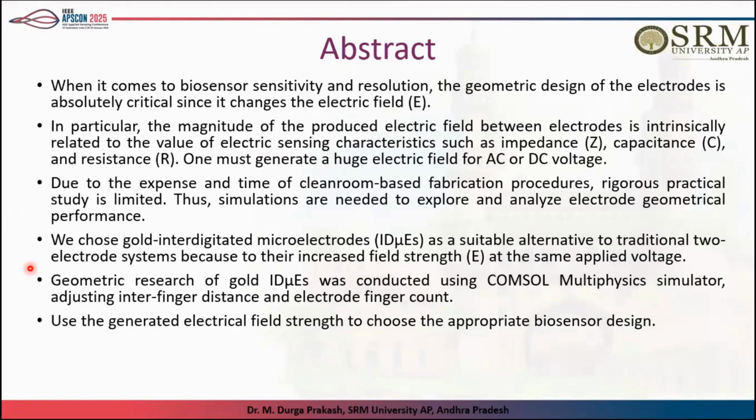The brief abstract of this work is as follows. We know that in any biosensor, we are looking majorly at sensitivity. The sensitivity matters, and also resolution. Particularly for that, we have designed and simulated the geometrical design of interdigitated microelectrodes, looked at what changes occur in the electric field in the sensors, and also seen the different sensing characteristics of the device, like impedance, capacitance, resistance, and other AC and DC electric fields.